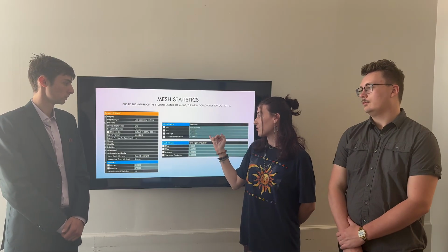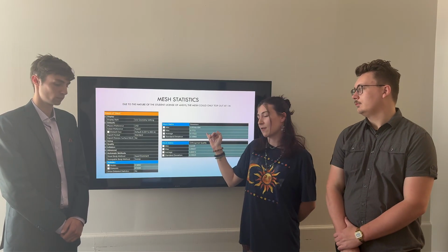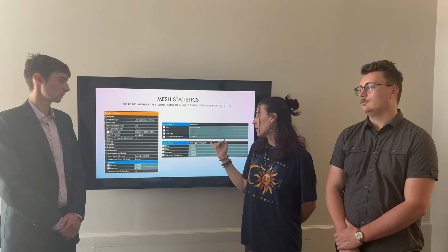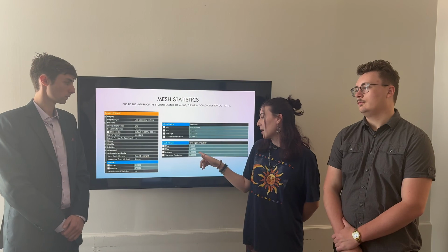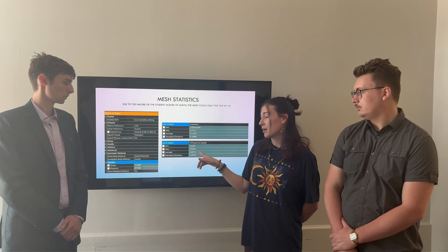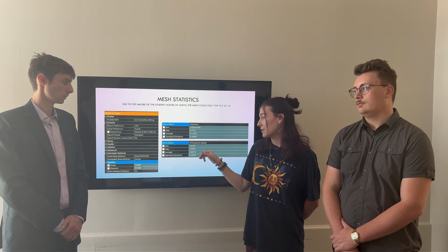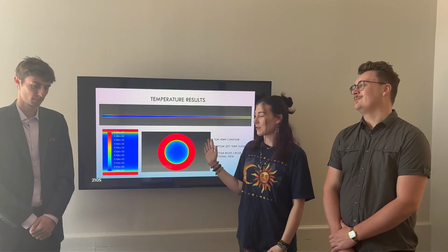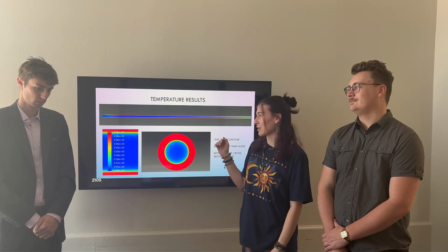The skewness, the average skewness is 0.17522, with the ideal being around 0.1. And then for our orthogonal quality, the average is 0.83013, with the ideal being 0.8. So that's pretty good. This is a graph for our temperature results of our simulation.